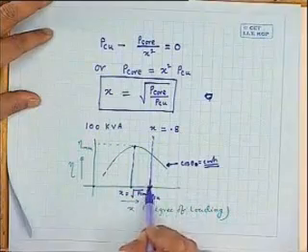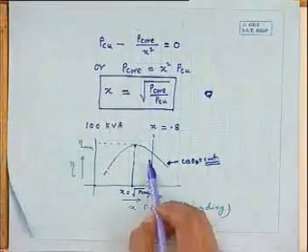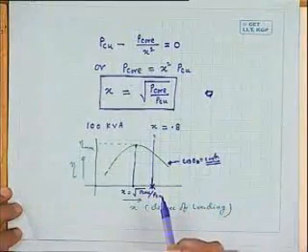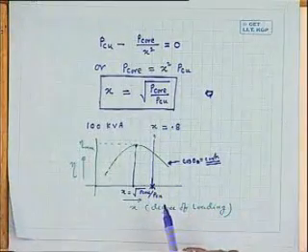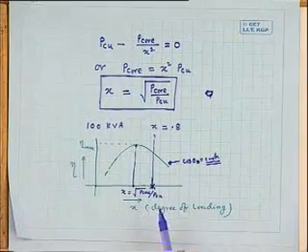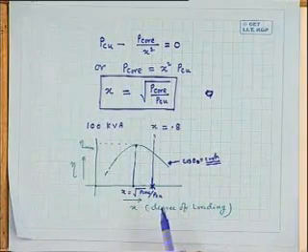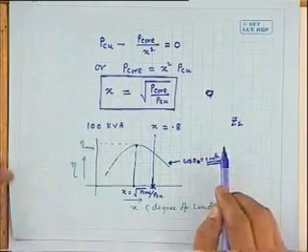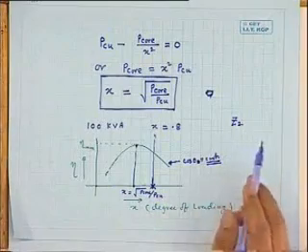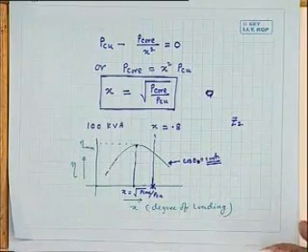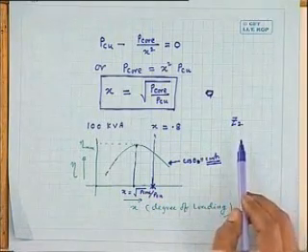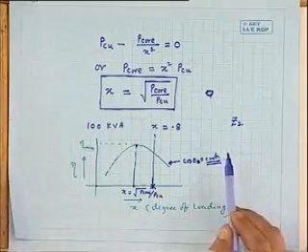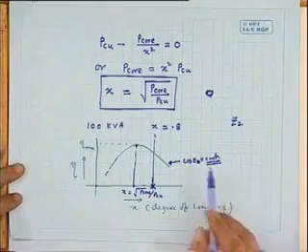Suppose at this value, whatever is the kVA, that x I will not change, and I will go on changing the power factor of the load. This also I can realize. Are you getting it? That is, the load impedance Z2 I will vary in such a way that the power factor changes, while the magnitude of impedance remains constant, so that kVA will be constant.